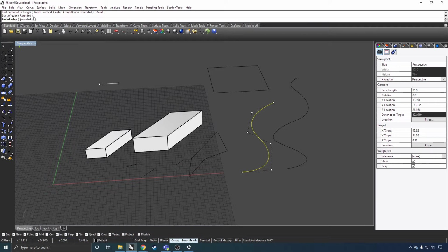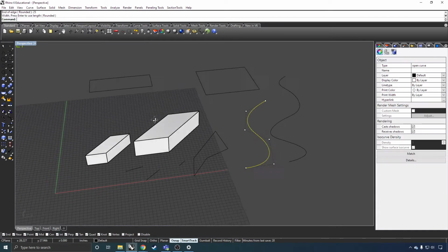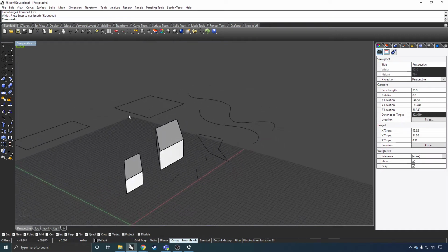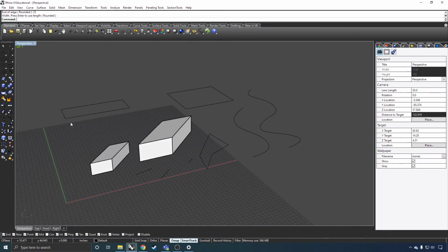From here, I can type in how much I want. There's a little cursor up here at the top, and it's essentially asking you for a distance or wherever that end is. So if I say I want 25, so 25 inches, I just type that in, and you'll notice that no matter what I do here, this point stays the same. Hit enter, and then say I want 10 the other direction. I can just type in 10. Because it knows a rectangle is going to be perpendicular, it knows it's going in that direction. Just be aware that if you flip over here, it's going 10 this way. And if you go on this other side, it's 10 this way. So that's a pretty simple way to make a shape like that.